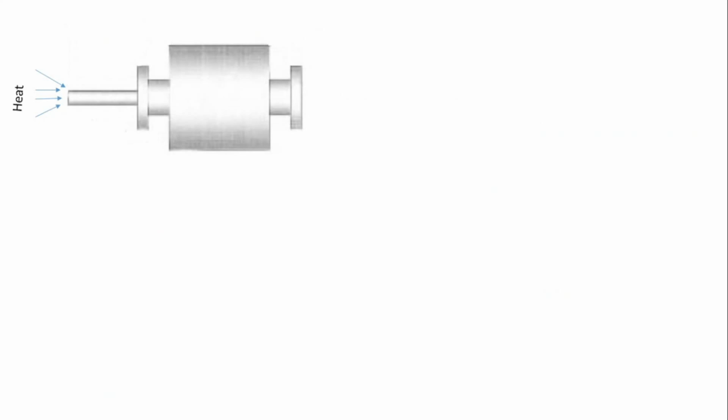So we're quickly going to illustrate this with an example. Let's assume this is a system and it's subjected to heat at one end. I want to assume that the heat is going to flow from the left side to the right side, from where it's being heated to the other extreme, in one direction and via conduction only. If that is the case, the next thing to do is to bring our governing equation. And this is our governing equation, for example. This is the one-dimensional heat flow equation, when heat is going to flow in one direction and there's a heating source.